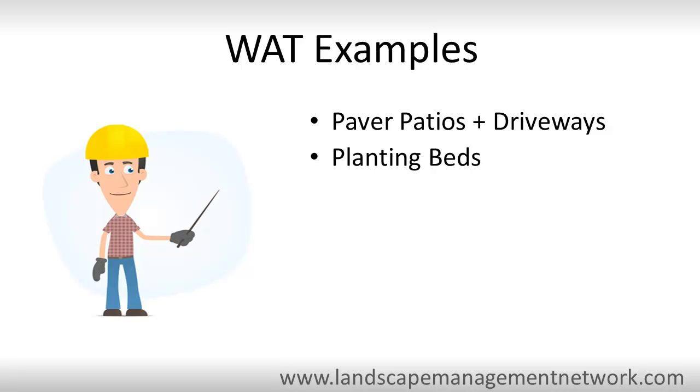You might also have a site prep and demo template. That could include all the components your estimators need to think about when you're starting a job. It might include things like time to lay out the site, time to prepare accessways, disposal charges, safety fences or tree protection materials, time and equipment to demolish existing structures, any of the costs that can be easily missed when rushing to get a price into a customer's hand. And remember, you don't have to use every item on every job, but this way your estimators have to remember to think about them, and that's what work area templates are set up to do.